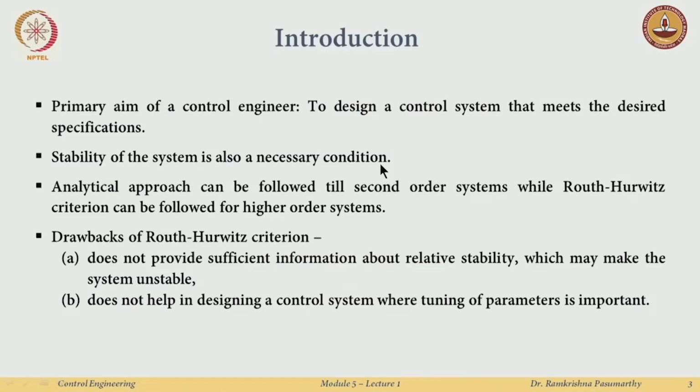In the transient response, I wanted to speed up the response, but with a constraint on the overshoot, so that I do not overshoot too much. I also wanted the system to have very small or no steady state error at all. But before I do this, I always wanted the system to first be stable. If it is stable, then I can look at performance.